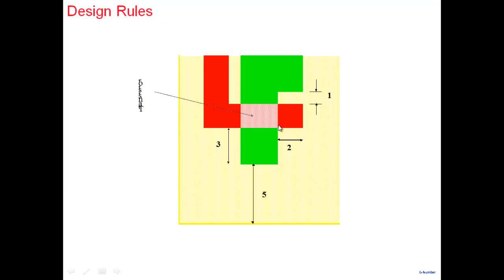So you cannot keep it perfectly at this particular point. You want a transistor right till that point, fine, but you can't keep it here because there are errors. One cannot do anything perfectly. So this edge may move left, or it may move right. If it moves right, it's okay, no problem. But if it moves left, there will be an exposed region where I will get N plus and the source and drain will get shorted. For that reason, the manufacturer is telling you, when you draw a poly, please extend it beyond that by 2 lambda. The manufacturer is sort of guaranteeing that there may be errors in the fabrication process, but if you extend it by 2 lambda, it's not possible that this edge will come back by 2 lambda. That much error I don't have. So this edge may go left and right, but it will not come back so much that a region gets exposed and the transistor source and drain get shorted. So the rule comes because of the limitations of the fabrication process, because of the errors that are inherent in it.